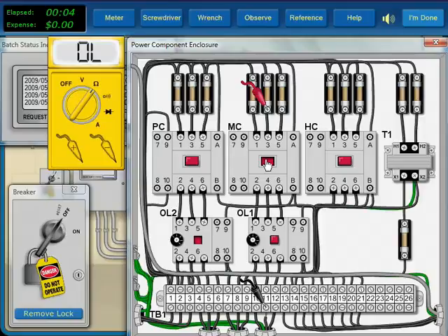We read infinite resistance. This means that the open is within the control box. We split this area in two at the bottom of the contactor. The low resistance reading tells us the open is above the test point. Testing at the top of the contactor with it closed indicates the contact is okay. Now, the only possible causes are one wire and its connections.